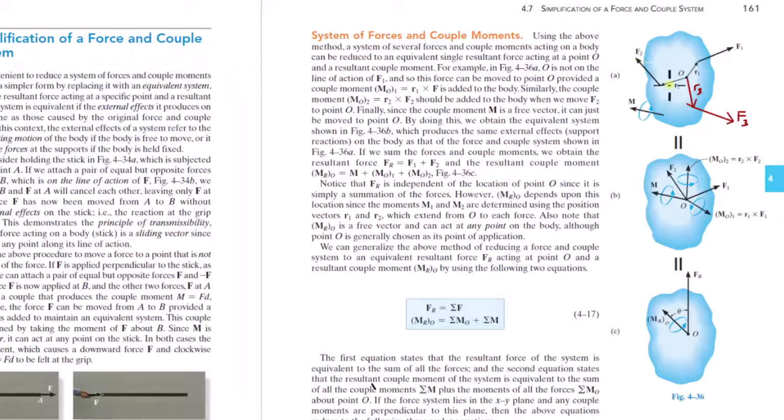So here there's forces. They have forces, and the force I added, and a couple moment. But there's no moments. So we have a couple, we have forces. What about the moments? Just the general moments about a point. Well, that comes from a force, right? You have the moment of this force about anywhere you choose. You have the moment of this force about point O, but that comes from the force. A couple moment is its own thing. So that's why they have a general state of loading here with some forces and one or more couples.